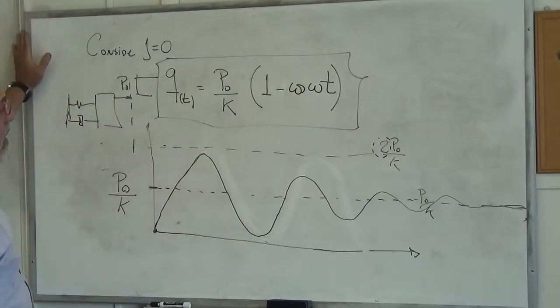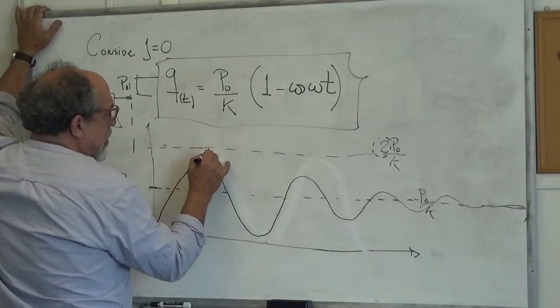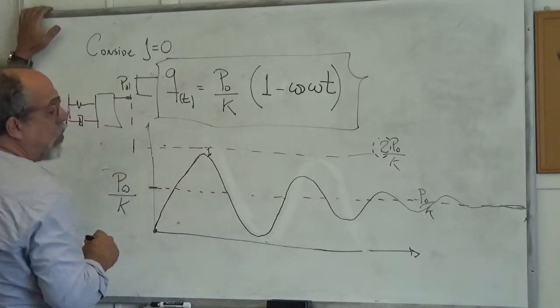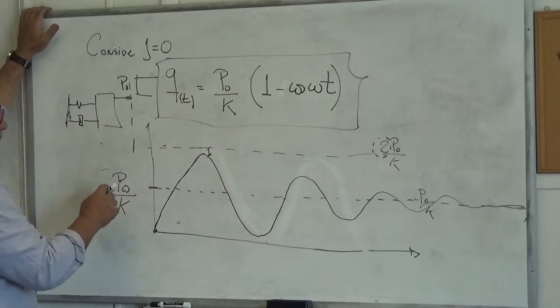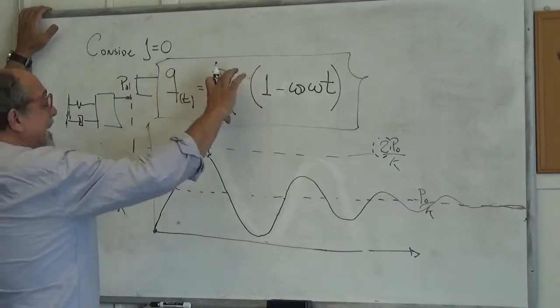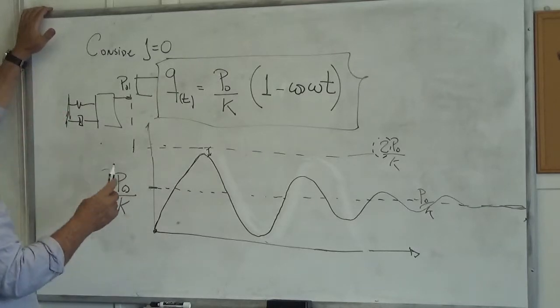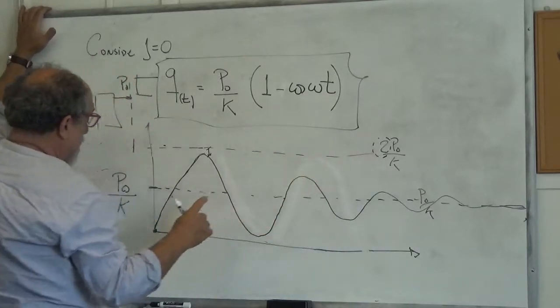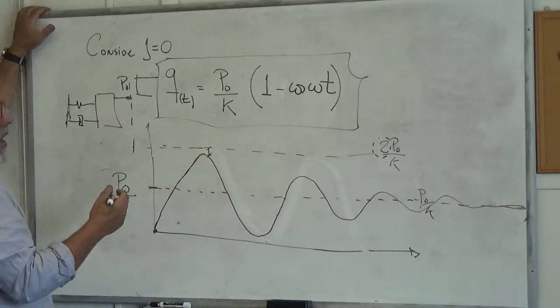One thing that is worth noting, although I'm not going to show it here, but we might do it in class when we meet, is that this difference, when you have damping, is actually quite small. The maximum response of the system to a blast is 2 times without damping, but with damping it is not that different from 2 times unless the damping is very, very large.